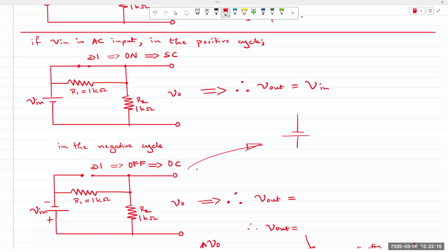In the negative half cycle, it's going to be minus plus, and my R1 and R2 are like this. My V out is here. This is R1. This is R2. Now, V out simply means, let's say you're taking a multimeter and connecting across R2 to measure. You're not actually connecting any component to R2. So R1 and R2 are in series because there is no other connection in the middle node. Okay. So if R1 and R2 are in series, current through those resistors remains the same.